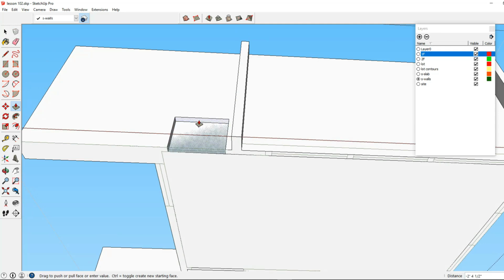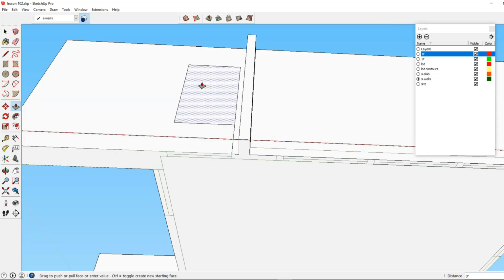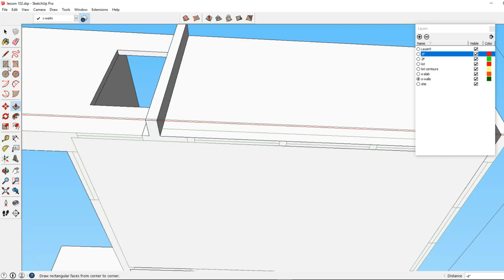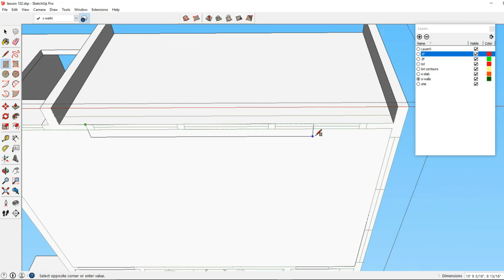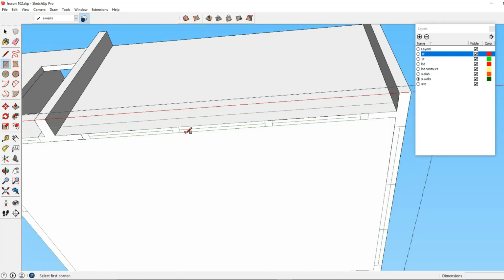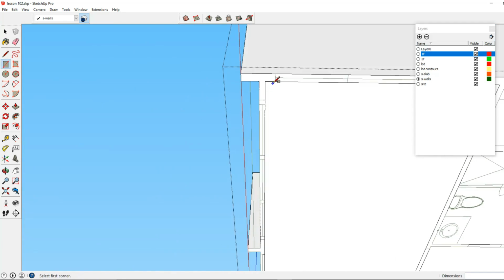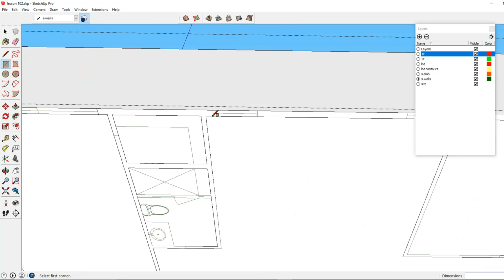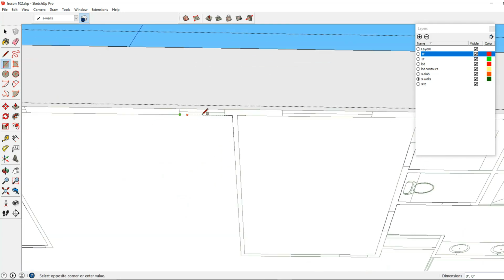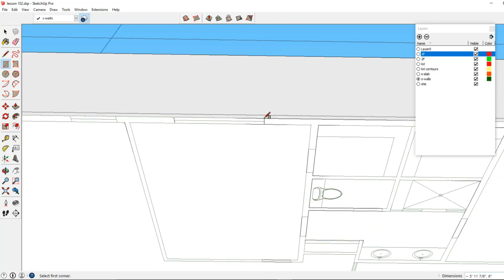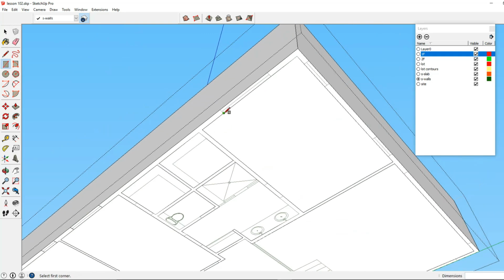And I'm only doing a 9 foot wall. I'm doing 9 foot walls in the second floor, so I'm going to use a header height of 7 foot here. And we'll make this one a pretty long window. We'll go to 5 foot here. And well, let's go around the plan and cut out these openings first. This way I'm not going from one command to another. While I'm in the rectangle tool, I could just do this all at once.